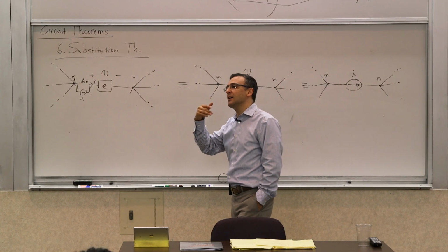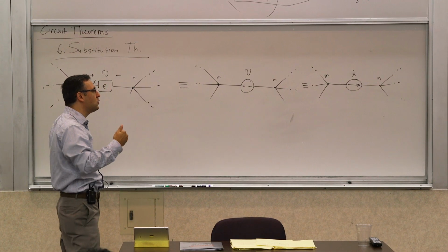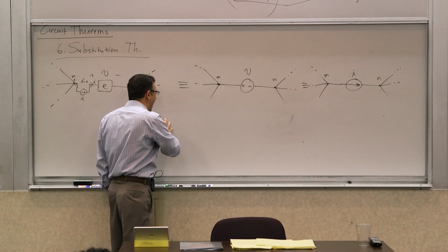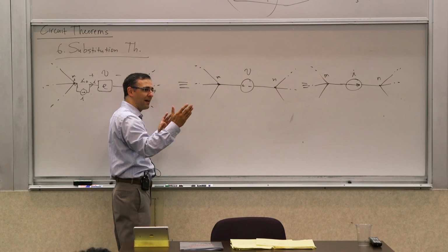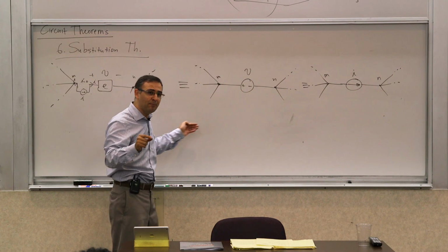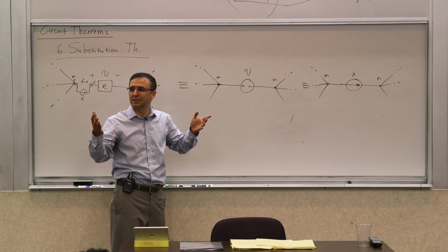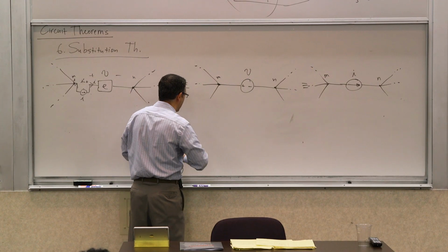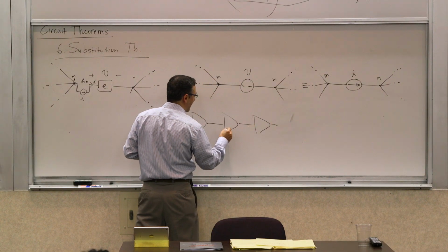That's fine. When you analyze those at a transistor level, what you do is calculate the gain of the first stage independently with the input resistance of the second one. So you take the input resistance, or the input impedance, of the second stage. Let's say you have 3 stages of amplification, and each one of them has an input resistance.